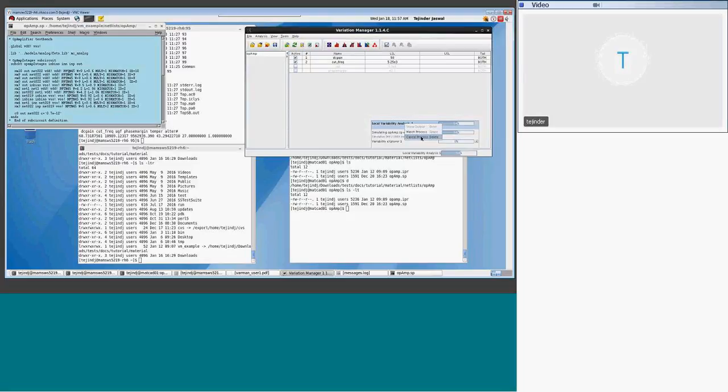This is the idea. You go with Monte Carlo, classical Monte Carlo, or you use variation manager analysis. As Monte Carlo was accelerated, Variety Explorer computes what budget is available, gives you the information and indicates the accuracy, and whether it needs more simulation to be more accurate or if it's good enough.